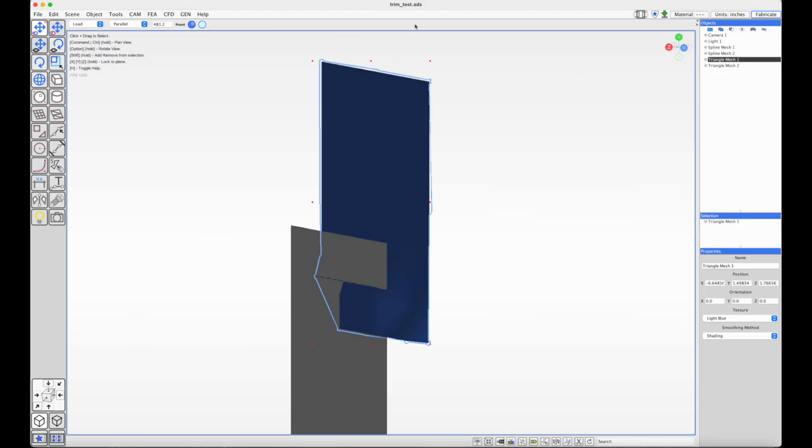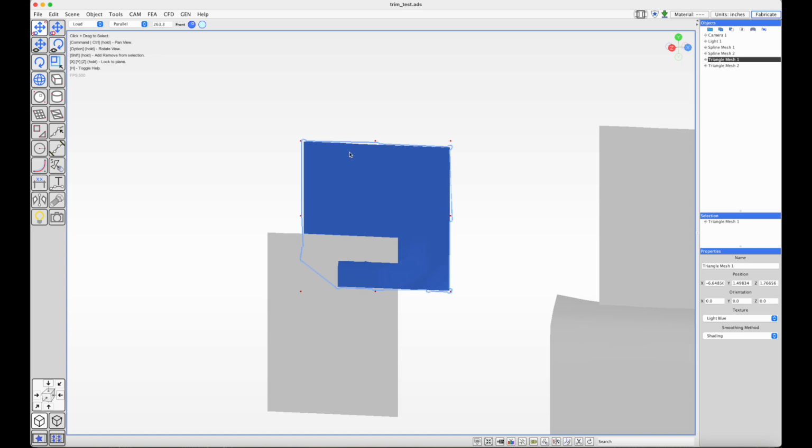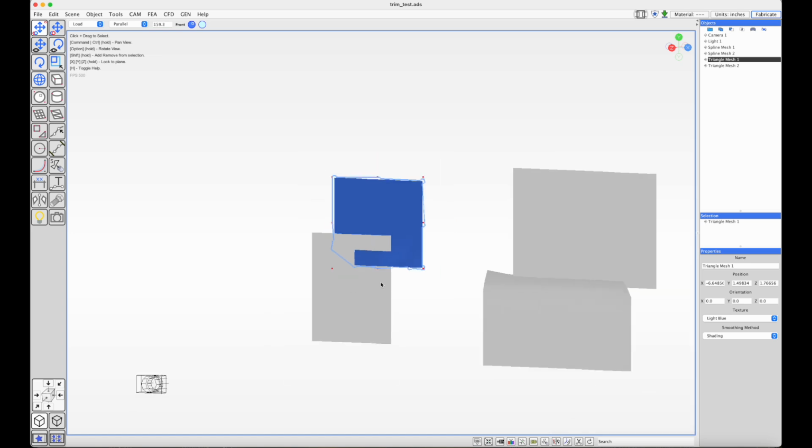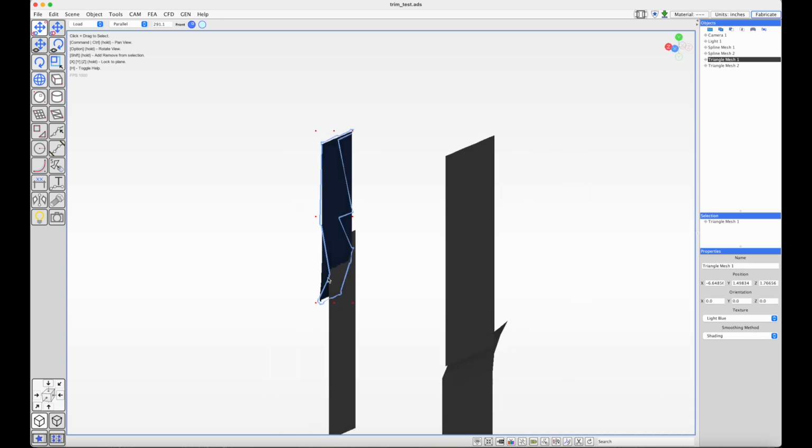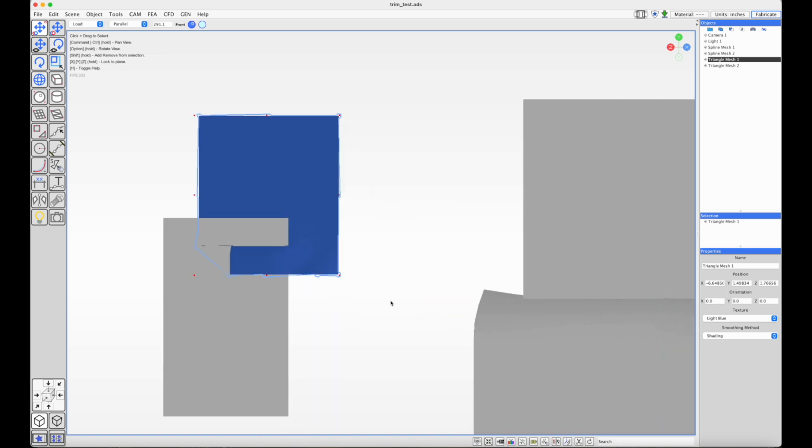This way we can construct mold forms and shapes using multiple different types of meshes and have them cross one another to get a clean edge and then just trim when we're done and generate the G code.